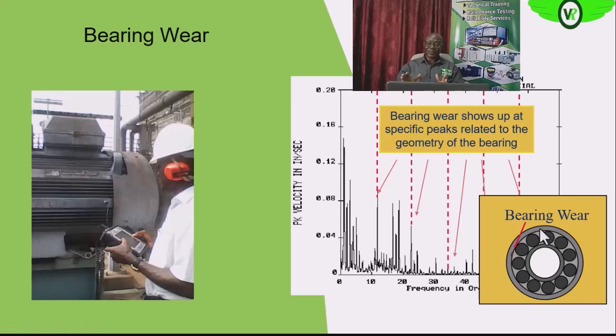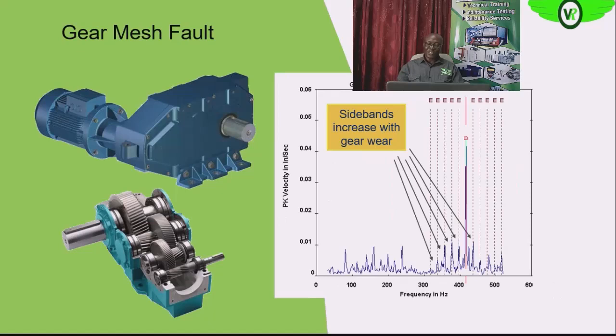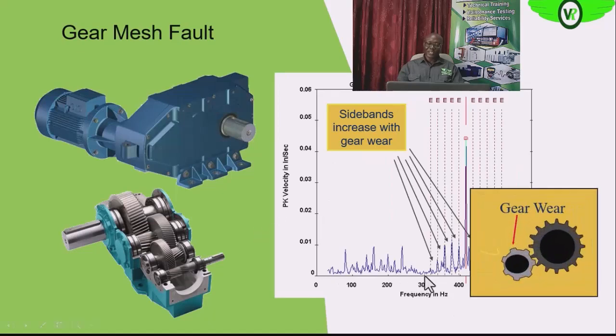you will see them at different frequency levels also, but close around that 11 times RPM. Okay, so we can also see gear vibration frequencies at those higher order harmonics, or higher order frequencies. So gear vibration, I mean to say, you see them at the higher order frequencies. Are we getting it? Which is notably around the gear mesh frequency areas.